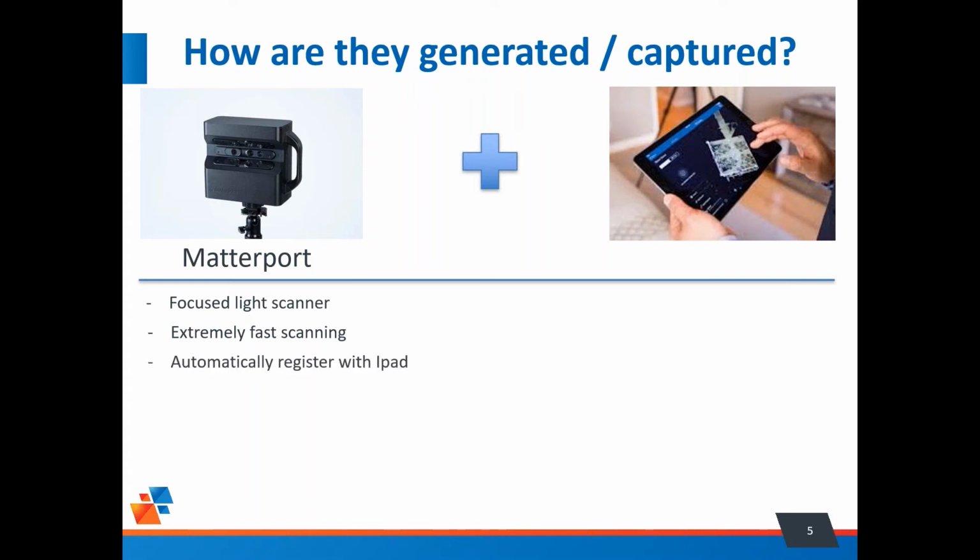It automatically registers with an iPad, and once you're done your project, you would then upload that information of all your multiple scan locations into the Matterport website, and they would create an area in there called your spaces. So that would be your individual projects. One of the really nice things about the Matterport is the speed. It's about 30 seconds to scan.